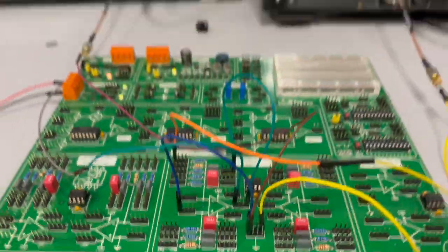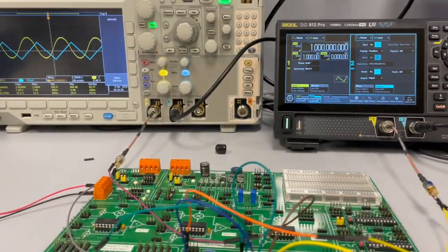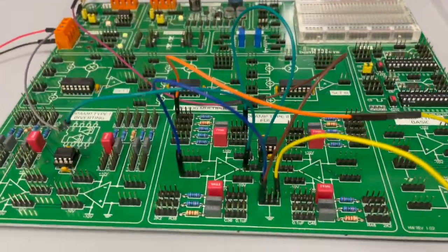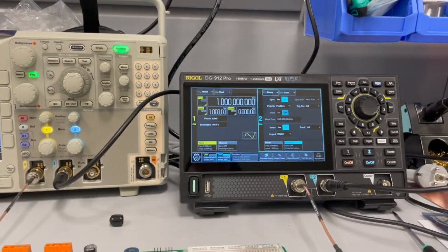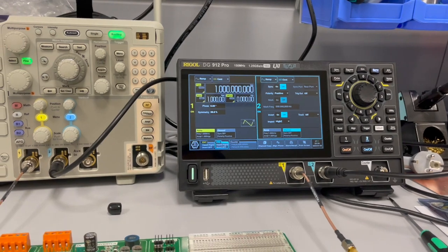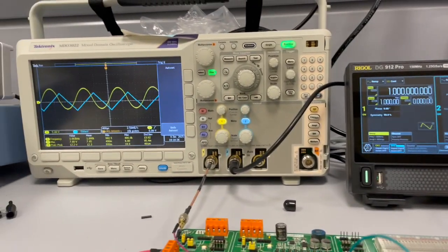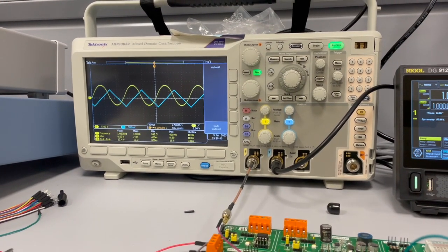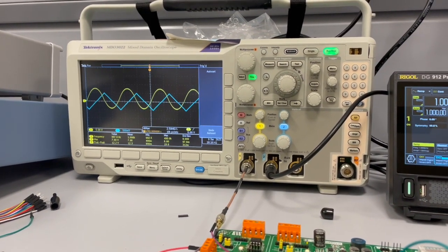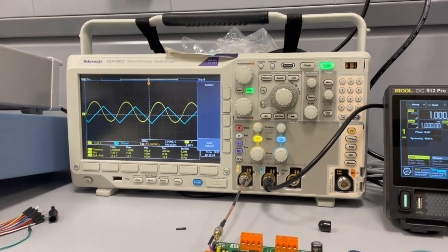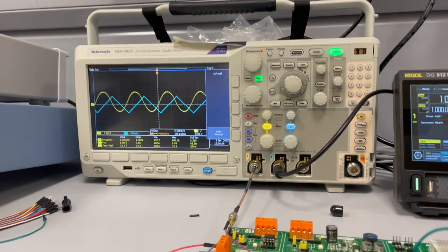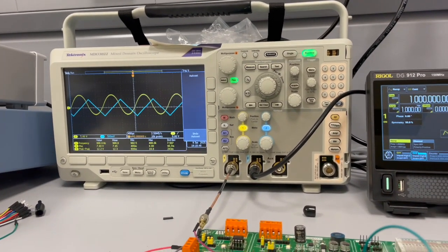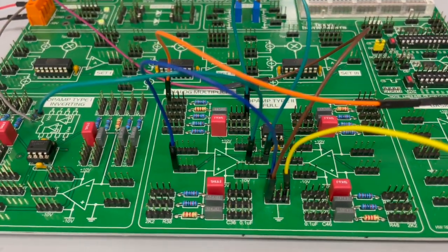So this is what the integrator is doing. Try to repeat the same procedure. Try to make the topology of the integrator. Choose sinusoidal, square, and triangle signals for the input, and record and take pictures and photos of the waveforms you get. Then make the report and record all the data that you recorded during this session of the integrator op-amp.